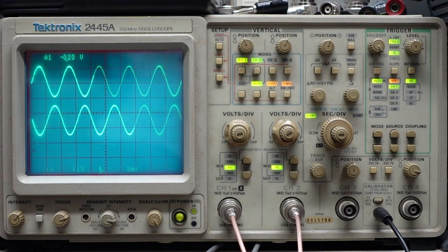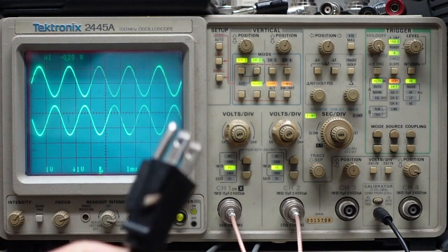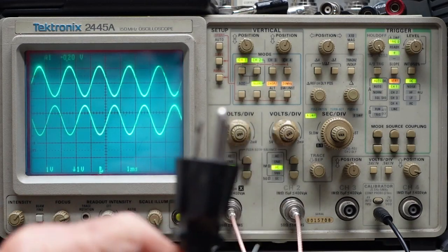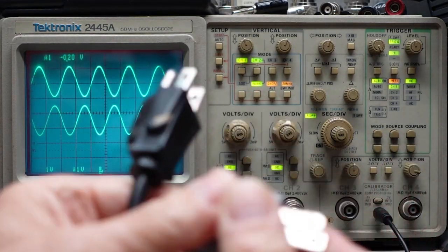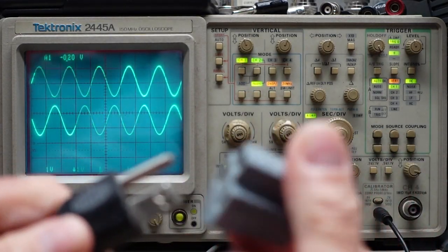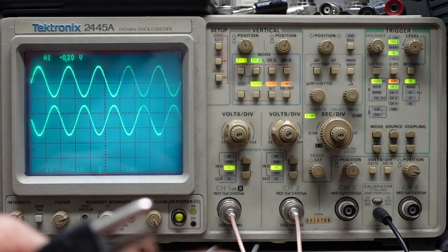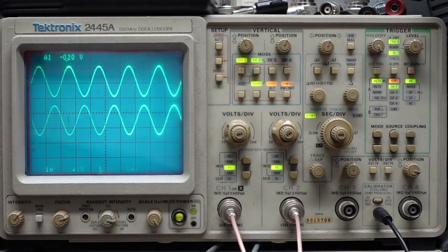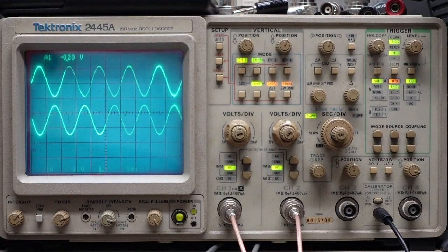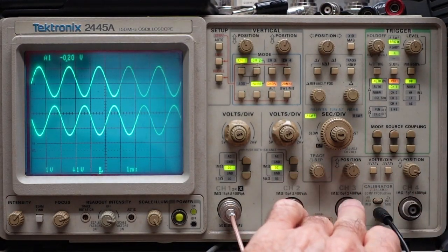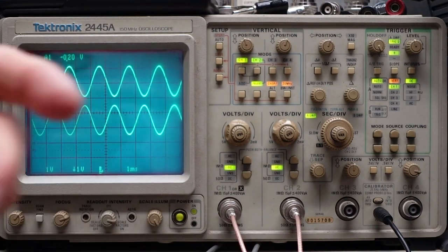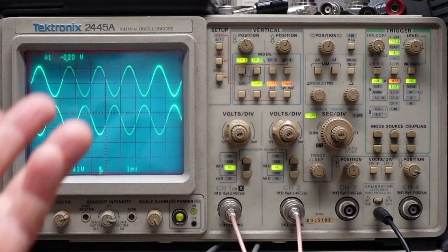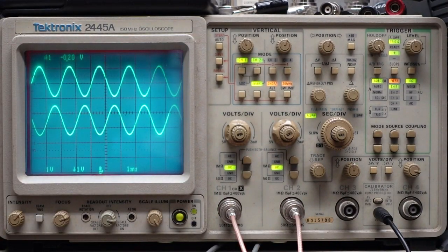We were always taught when I was in school to float the oscilloscope, okay? And what you do here is you take your plug for the scope and you put one of these 3 to 2 prong adapters on it so that the ground is now floating. This is not recommended. This is a dangerous practice because it can leave your BNCs at a line potential or 120 volts. It's a shock hazard.